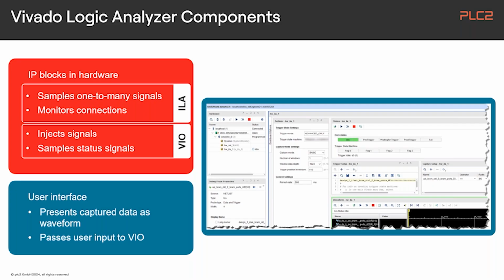So for example, here I see an idle state and a control menu bar where at least the signals can be observed in the waveform view or in the panel view of the VIO. The ILA runs at full speed, so actually this is a real-time capturing, but on our host PC we have a JTAG-based slow interface where captured data can be streamed out in the synchronization of our host PC.